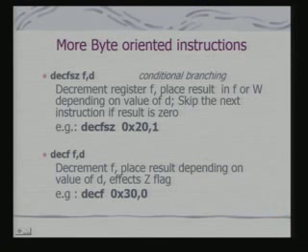What is the motivation for designing such instructions? Because similar instructions you will find in other microcontrollers and processors targeted for embedded systems. This increases what we call code density. That is, instead of using 2 instructions, one instruction to decrement and then jump, you are using a single instruction. So, the number of memory locations that your code would occupy can decrease. If it decreases, what does that mean? You require less memory, and obviously when you are working in an embedded system, you try to work with less memory, and less memory would also imply less power consumption.